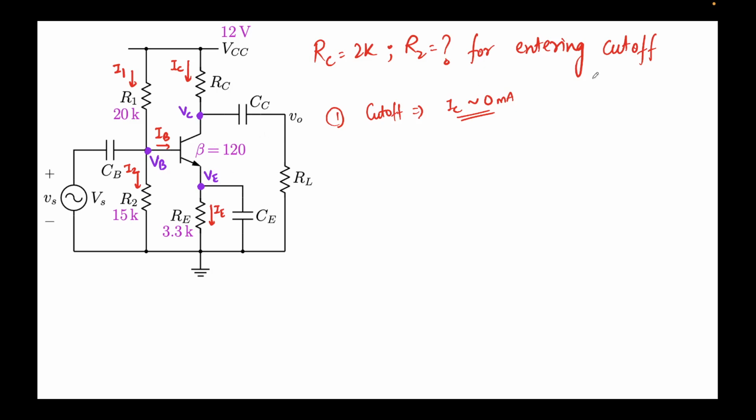If you remember the earlier slides which I showed you, these were different curves, and just at the very bottom, in the orange region, this current you see, this was IC versus VCE, is very low, so we'll assume that the current is 0 milliamps. So there is no current flowing through here now.